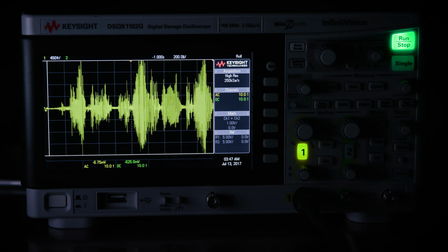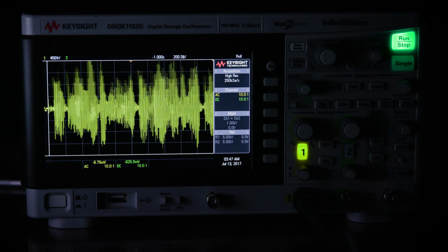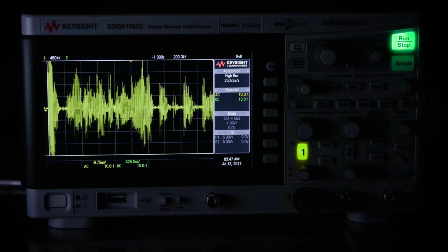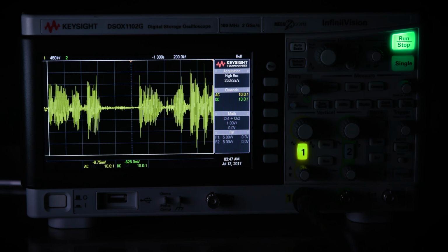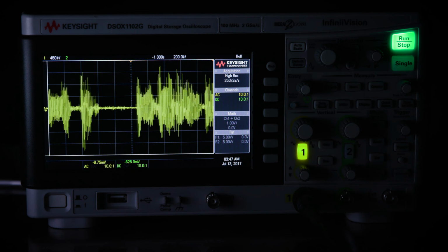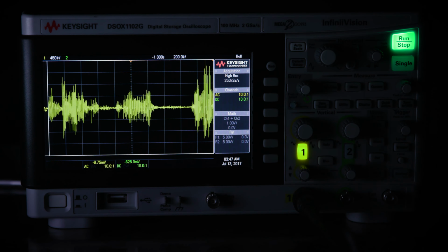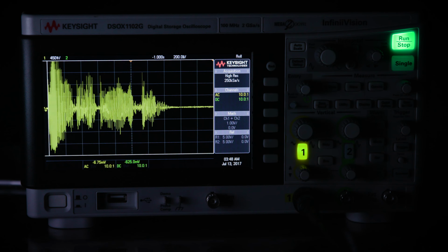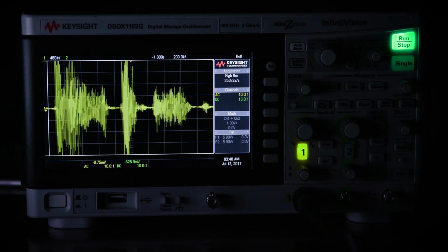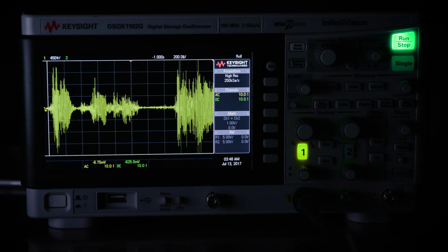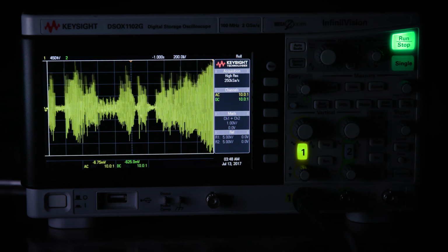Let's see. So it sounds great, right? I can take my inexpensive A to D converter. I can interleave a bunch of them. I don't get more bandwidth, but if I put a sampler out in front, I can get more bandwidth too. What are the drawbacks? Well, getting everything to match up is hard.